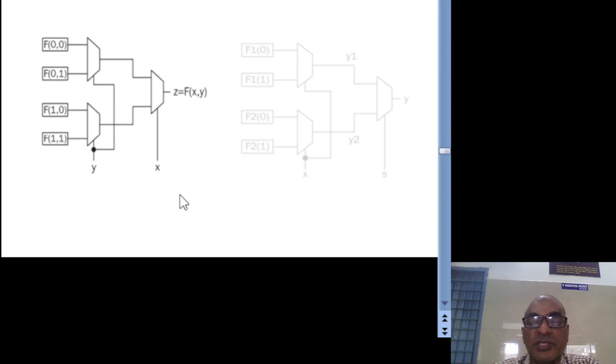Now I am going to stop this one. You can implement all our two variable functions which I have shown in the previous slide, like the OR gate, AND gate and XOR gate realizations, using these 2x1 multiplexers. Already I have shown the 4x1 multiplexer, but now you implement. I have given the general structure of how to implement the same using 2x1 multiplexers. For those three gates, show the result, the lookup table realization using 2x1 multiplexers. Thank you.